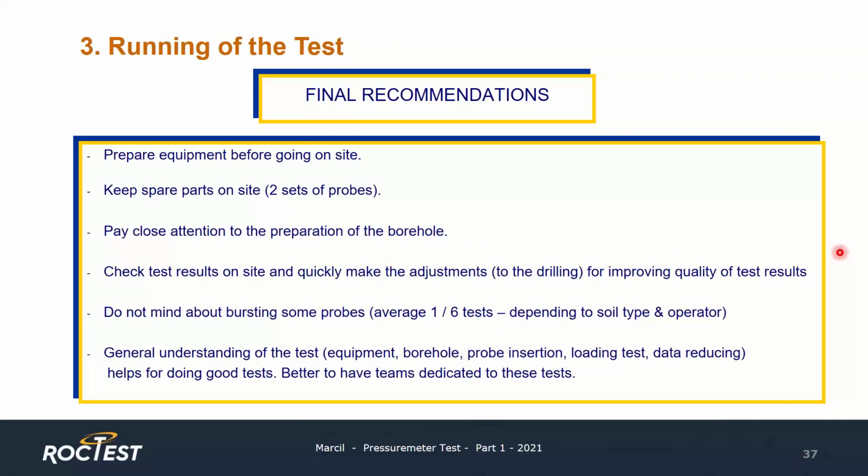And some final recommendations related to how to run the pressuremeter test. First, it's a very good habit to prepare the equipment before going on site. It will help to practice and also to make sure that the equipment is working properly, because you don't want to find out on site that the equipment is not working properly.